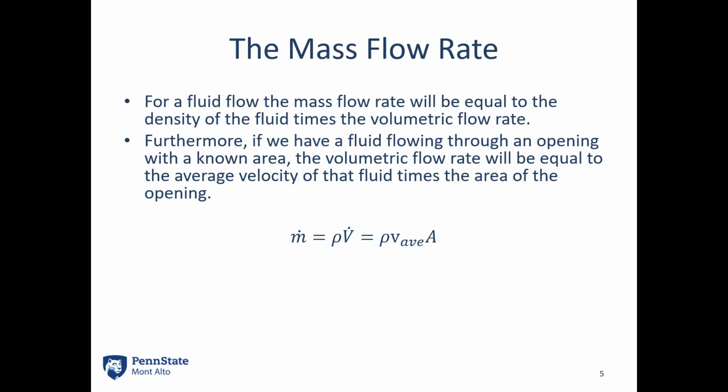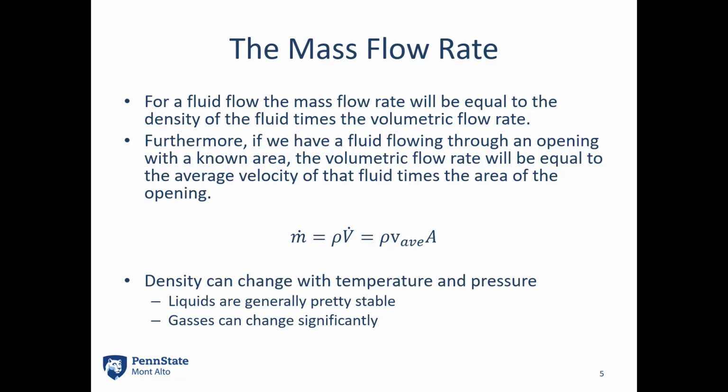Whatever you have in your problem, you're going to need to figure out your mass flow rates first. And do remember, density can change with temperature and pressure. Liquids are generally pretty stable. Density is not going to change a lot in these devices, but gases can change significantly.